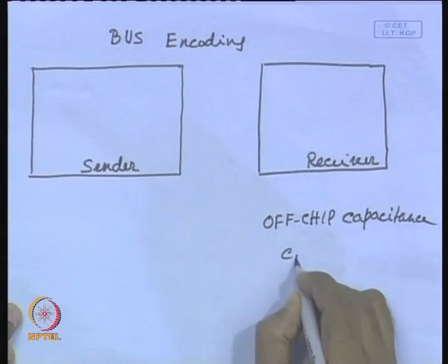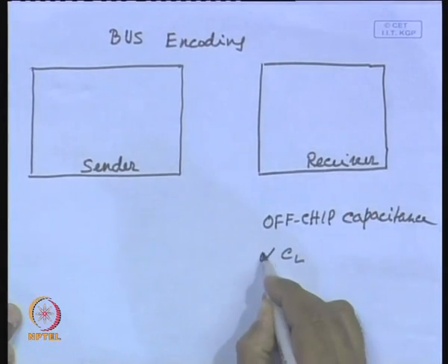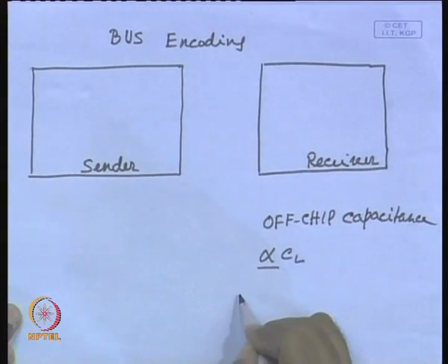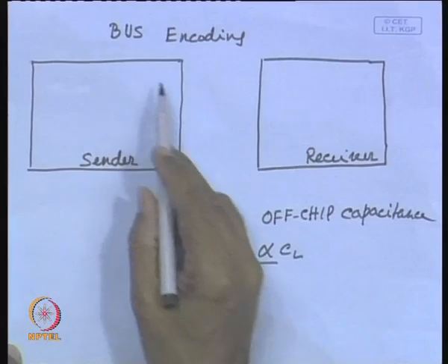So, you can see it increases significantly, several orders of magnitude higher, and obviously, as you know, the dynamic power dissipation is proportional to CL, and as the capacitance is very large, you have to minimize switching activity. So, switching activity has to be minimized so that the dynamic power dissipation is reduced. Now, in this particular case, how will you be doing it?